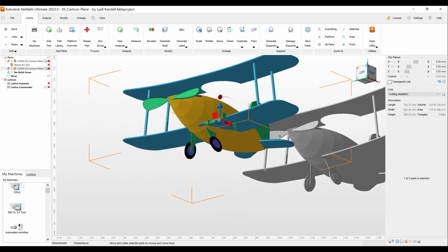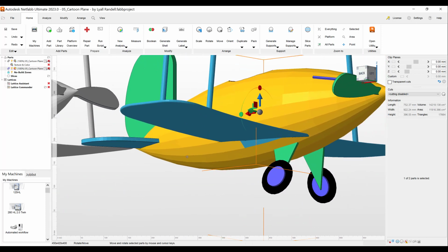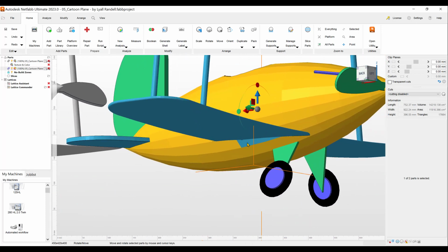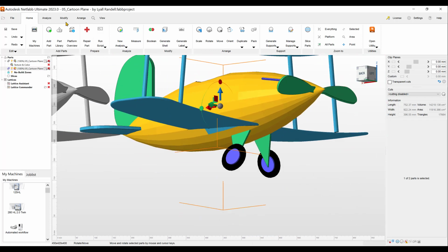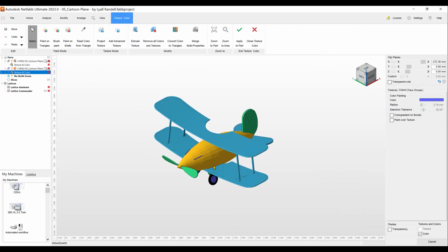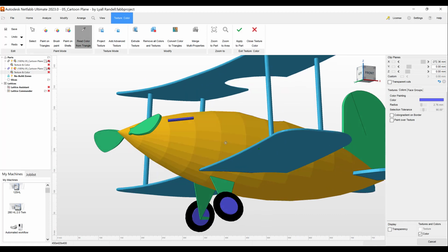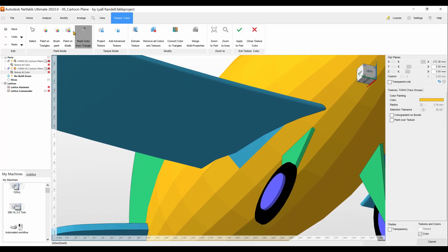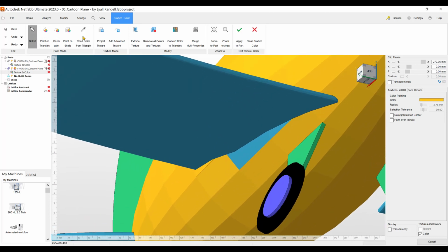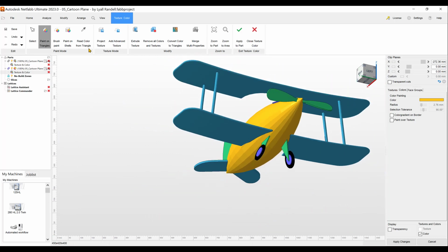But just to show you the eyedropper here, let's say, for example, you painted a part and you got a little overzealous here and you mark some areas too much, you can go in here to the modify again, go to textures and colors here, and we can use the eyedrop icon, for example, where we want to make this the yellow. We just select that, go here, and then we can mark triangles, or just slide it over there and fix that little area up using the eyedropper.